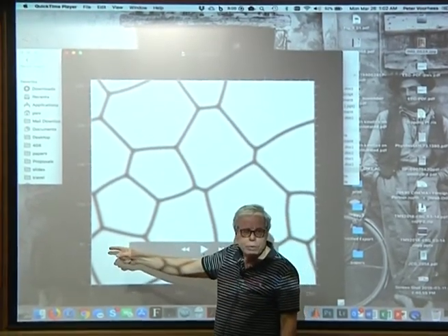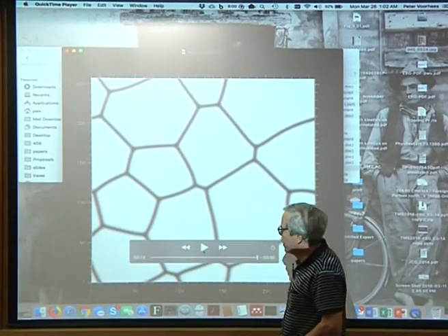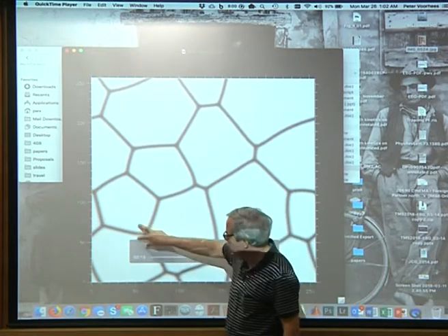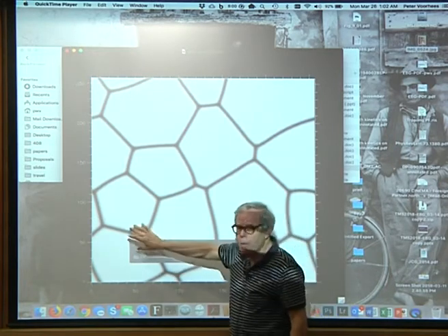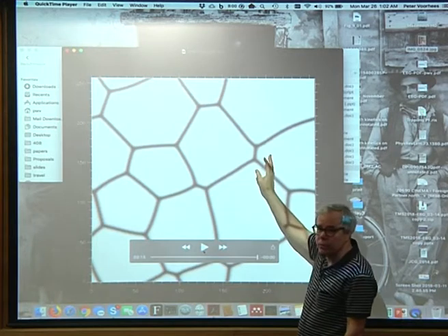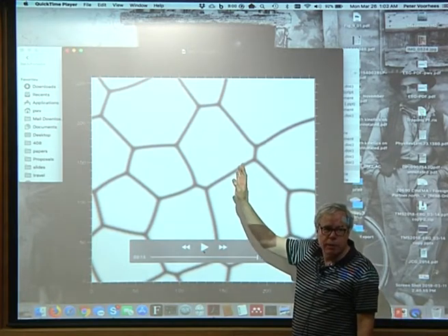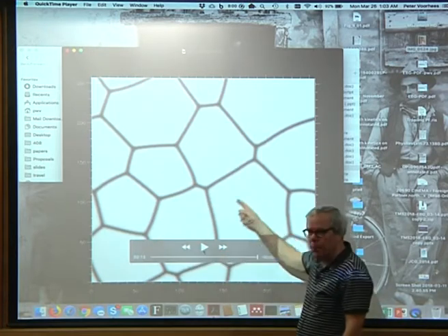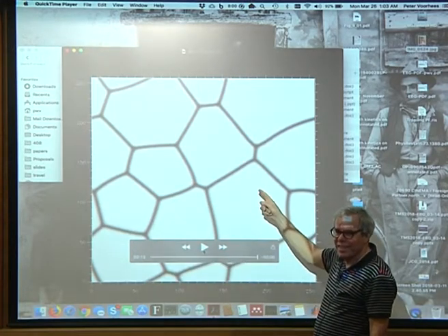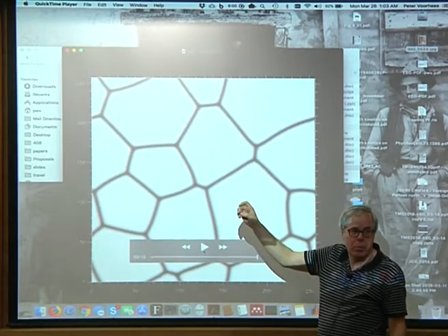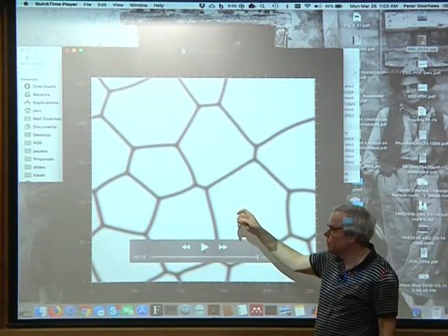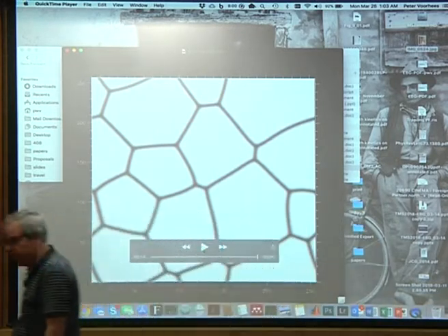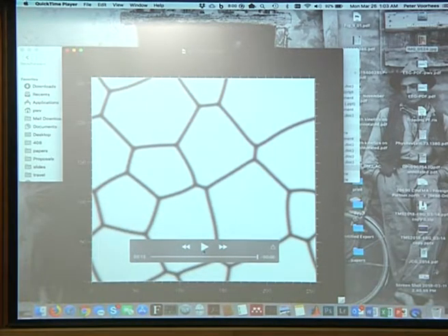And so what people have also done is written codes that only allow the order parameters to evolve in certain regions near the boundaries, and you don't worry about every place else, to speed up the codes. The problem there is that you have to figure out how far from the boundary is good enough. And that's also another parameter in some of these codes that you should watch out for. But nevertheless, it pretty clearly gives you something that looks just like good old regular grain growth, which is kind of nice.